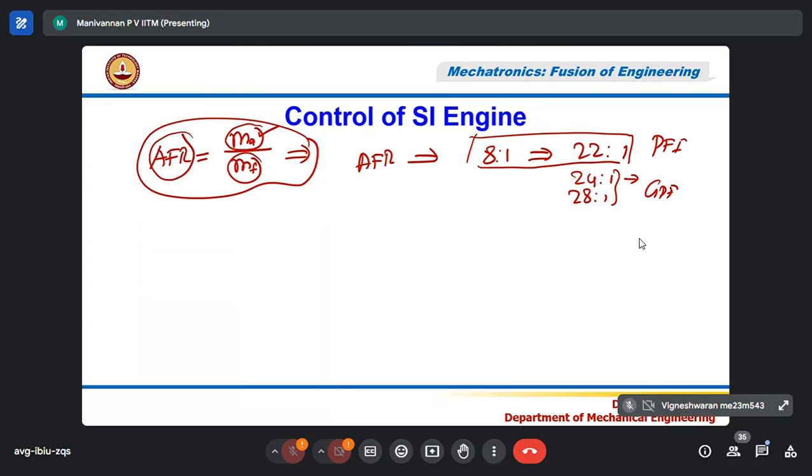So now the ECU can compute once the volume is known. How is the volume computed? Using the TPS signal. The TPS sensor gives alpha, that is nothing but the throttle angle. Once that is known, using the throttle equation, the ECU can compute the volume of the air.